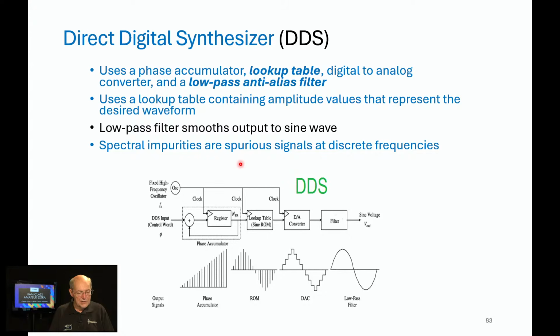So in a radio that's using direct digital synthesis, sometimes with the antenna disconnected, you will, on some of the ham bands, occasionally be able to see a signal that's sitting there all by itself that happens to be a spurious signal coming out of the direct digital synthesizer. And I've seen radio manuals that say that on these specific frequencies, you may hear a birdie, as they call it. And that's what those are.